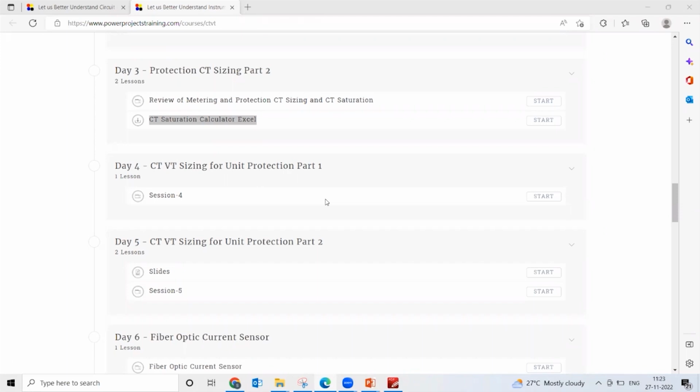That is nowhere practical, in fact. Again, directional overcurrent also, I have not really worried much about it, because in general the systems are inductive in nature. So with respect to the voltage, the current lags by almost close to 90°, right? Assuming R is 0, but R has some value. So this angle will be in the range of about -80 to 90. So whether the fault is forward or reverse can be easily identified, and errors may not have that much significant impact.